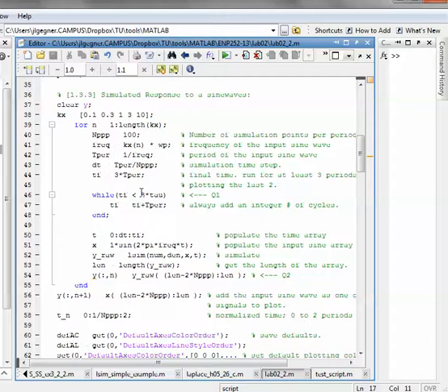Here you have to look at the procedure for what I'm asking you to do. Essentially, I want you to run the simulation. I want you to apply a sinusoidal excitation to your filter at it looks like 1, 2, 3, 4, 5 different values from 0.1 to 10, and apply different sinusoidal frequencies, and then plot what is the sinusoidal steady-state response. Now here's the caveat. These number values here were chosen based on the first order RC low-pass filter. I don't know if they make sense for the Sallen-Key low-pass filter that we did in Lab 2. So I'm going to leave it up to you, and maybe Mr.